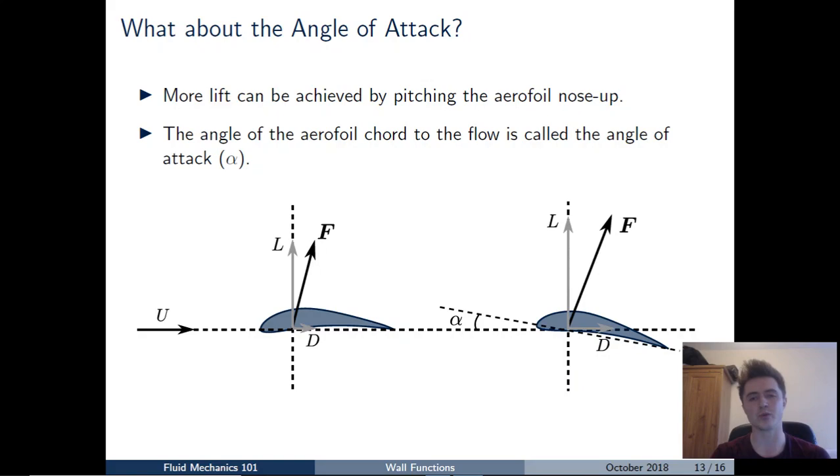So what happens when we pitch the nose of the aerofoil? Actually, what we find is something very interesting. If we take the aerofoil section and we pitch it nose up, then we change the angle that the flow is incident on the aerofoil, and that changes the entire shape of that pressure distribution acting on the aerofoil.